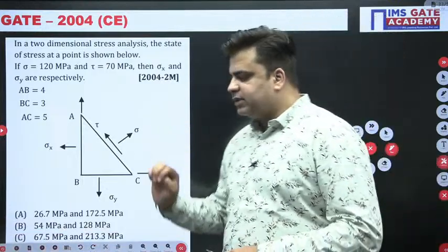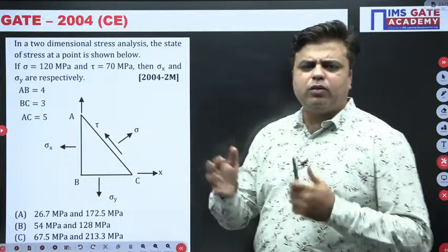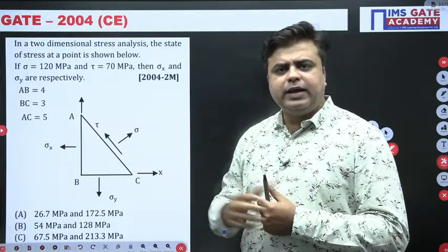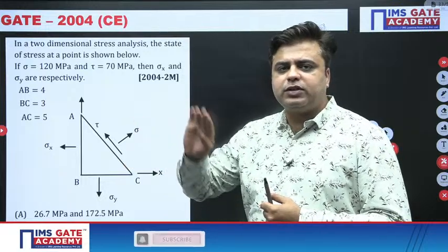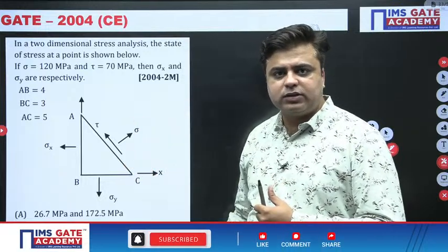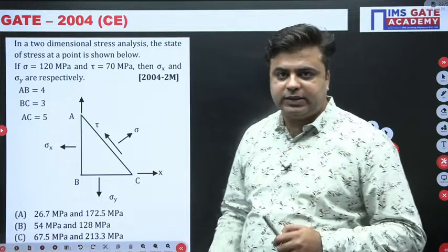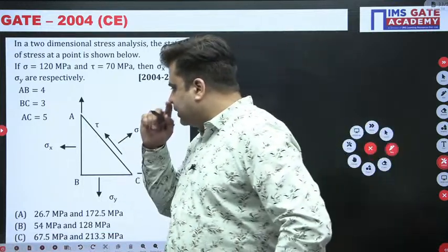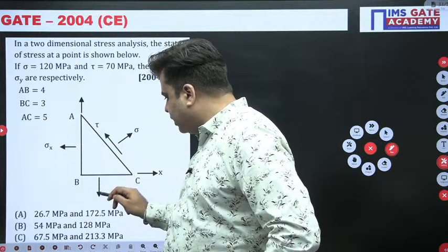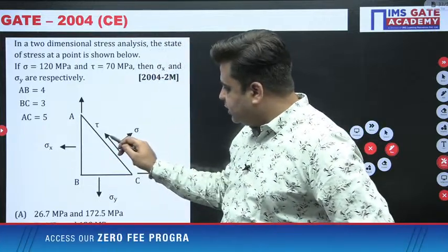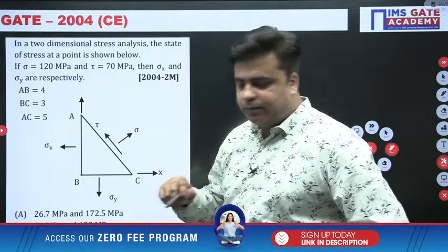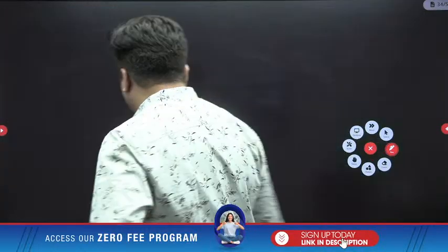For solving this question, you will have two or more methods, right? Either you can apply the formulas of stresses on the oblique plane and you can solve this. We have one more easier method that will simply require the use of basics, right? First of all, you need to understand this sigma x, sigma y, this normal stress and shear stress is acting on which plane. So for that, let me draw one 3D diagram like this.